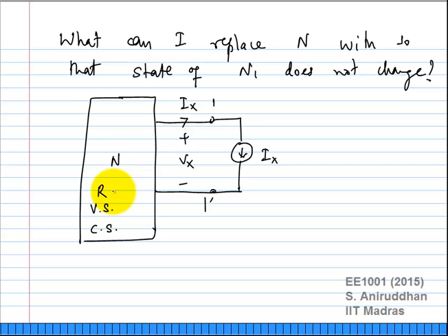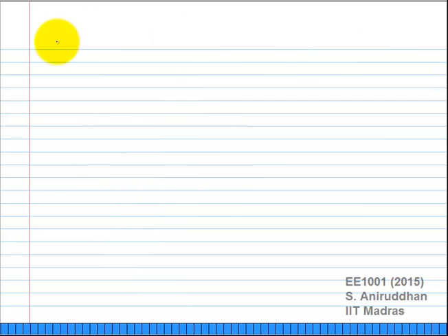Is that clear? Any questions on this? So I am going to apply superposition in two steps. First step, I am setting Ix to 0 and I am going to apply all of the internal voltage and current sources. The second step is setting all of the internal voltage and current sources to 0 and applying Ix only. A linear combination of these two will give me the steady state solution. Correct? For what? What will it give me the steady state solution for? For what the relationship should be between this network and these voltage and current values. Okay, so let us quickly look at this. I will just redraw it slightly differently. So I am going to apply superposition.